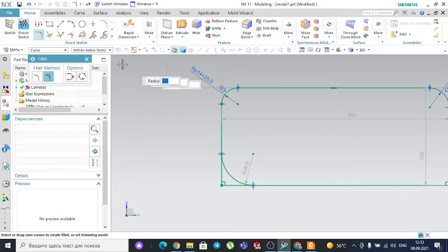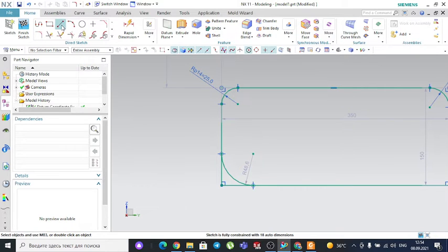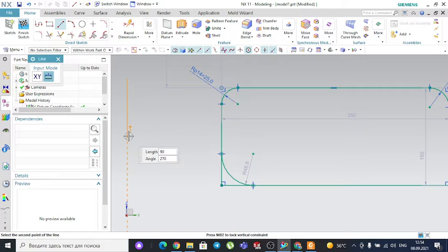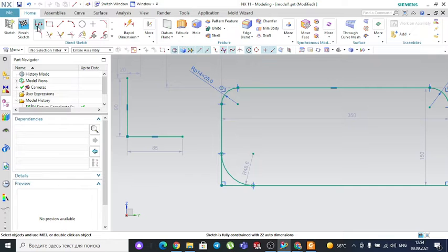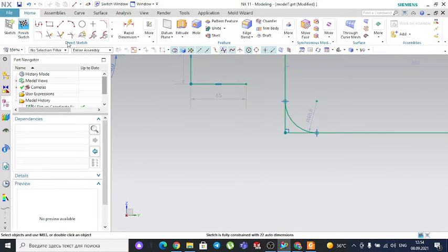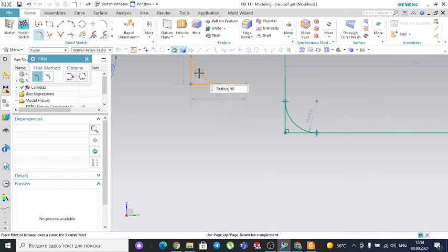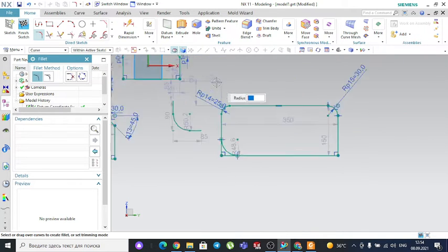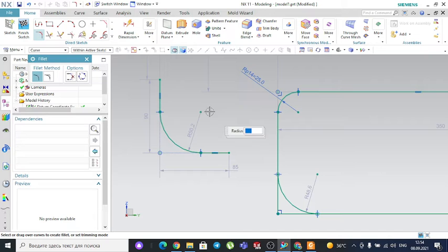so it is better to delete the corner with this method, trim. There is a second one, untrim. The trim method is the most useful and most effective way of making the fillet on the corners. Also, you can make the corner or the chamfer with the intersection of vertical and horizontal lines as well. So, for example, check the fillet, this one and this one, you see the radius is created. The same way you can create the chamfer for such an intersection of horizontal and vertical lines.